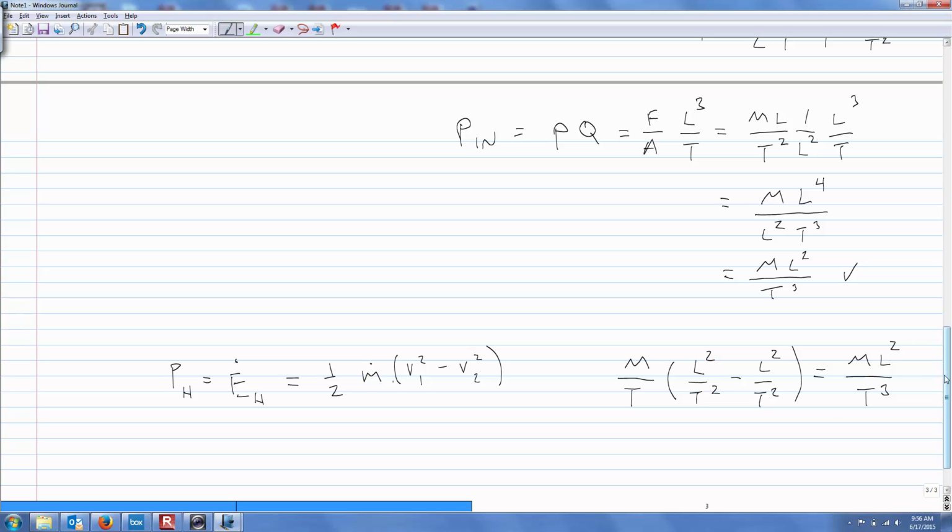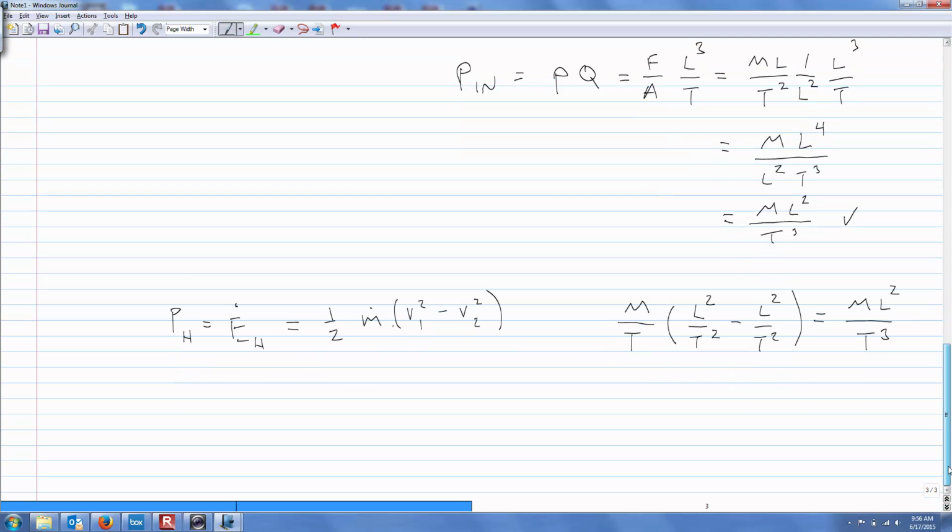Okay, so now I think we can deal with your system in a very concrete way and figure out how much theoretical power we're going to get out of this thing. Okay, now we're in great shape. So let's do a little estimate as to how much power we might get going in. In this case, the 1 is the same as velocity in. Maybe I'll just rewrite it here: equals 1/2 m dot (v in squared minus v out squared). So don't erase it. It's just another way of writing it.